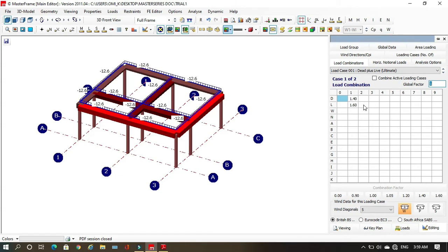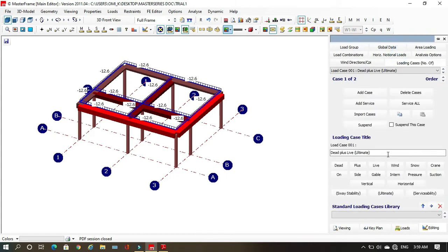But if you want, let's say you have another combination of load that you want to use, you can come here, you see wind load and every other load that you see, and they're here: live load, dead load, snow, crane, and all of these loads with their factor of safety, so you'll know what you need to use. Okay, but I don't want to use any of this. I'll just use the default one, which is 1.4 for dead load and 1.6 for live load.